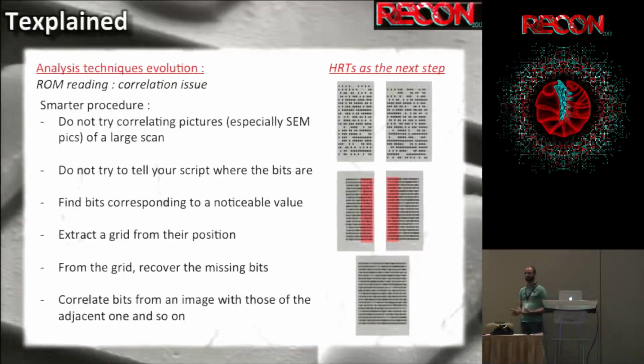How do you design a chip without a grid? It would be insane, like how do I place things? The things have to match on different layers and everything. So they use a grid. The trick will be to detect the grid, as we just did on this ROM. And when we have the grid, we can do a lot of things, finding features and putting them all together.